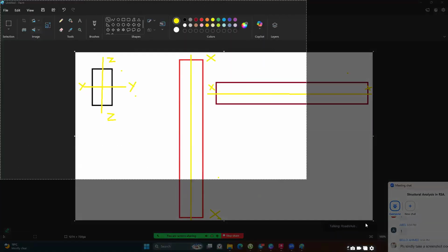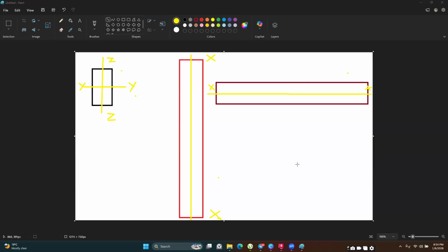So I'll just repeat this for clarity. We have three major axes for the beams and the columns. x is along the length, and x along the columns is also along the length. Because it has 2 dimensions for the cross section, you have the shorter direction, which you'd consider the width, and the depth. The direction where you expect the member to have more stiffness is going to be the Z, and then this Y is going to be the minor axis.